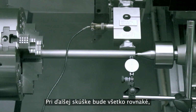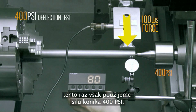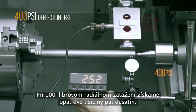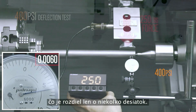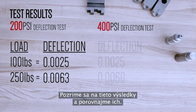For the next test, everything's the same, except this time we're going to use a tailstock force of 400 psi. At the 100 pound radial load, we get 2.5 thou again. And at the 250 pound radial load, we get 6 thou, which is only a few tenths different. Let's take a look at these results side by side and compare.